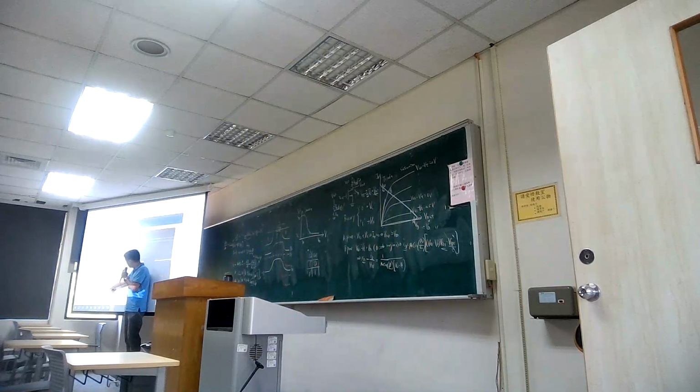So if you connect the thing here, you can see that we have the terminal. So here's what we mentioned. There's the body. So for this terminal, they grounded it and then linked it with an arrow to the body. And then here we get 1 volt. And for 1 volt, it should get a conducting current. So if you compare the difference between 0.7 and 1 volt, you get a sweeping of the input voltage of V2. In PSpice you can sweep it, so we can draw the curve as the V2. Here's the voltage versus the current.